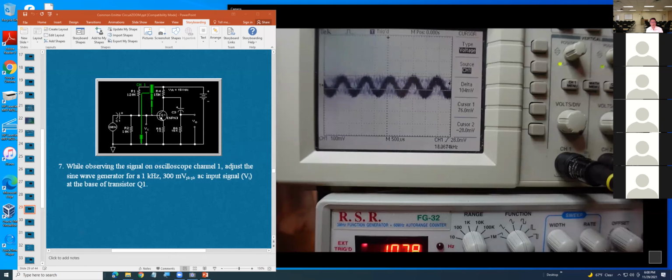Hopefully the scope can do it for you, but for a small voltage, the scope normally cannot measure correctly. That's why I tell you, you have to use the cursor. With big noise, the scope will measure from the top to the bottom, and that will be wrong.